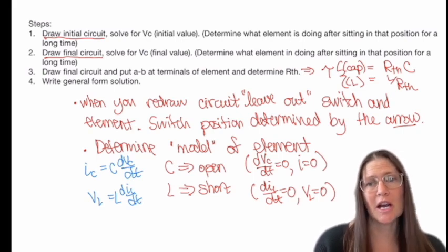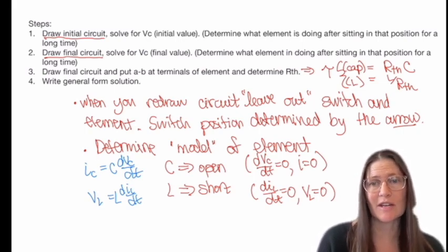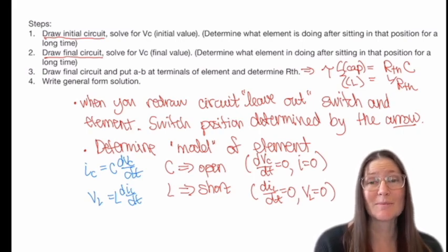And then for a capacitor, you're going to leave it in, you're going to assume that it's been sitting for a long time, so it's going to be open. An inductor, you would assume it's been sitting for a long time and shorted. And then from there, you're going to solve it to find voltage for a capacitor and current for an inductor.